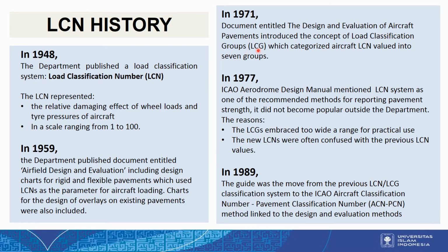So LCG is the load classification group. The LCG categorizes aircraft LCN values into 7 groups. And in 1977, the ICAO Aerodrome Design Manual mentioned the LCN system as one of the recommended methods for reporting pavement strength. But unfortunately, it didn't become popular outside the UK.